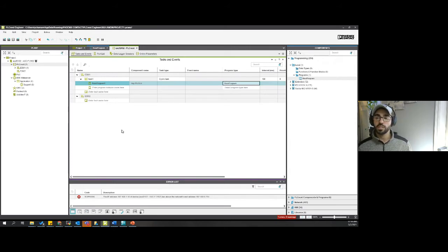We just need to make sure the OPC UA has the right configurations for this demo, okay? And again, OPC UA configurations will be different depending on what kind of OPC UA client you're connecting to. So the PLCnext controllers are OPC UA servers. So they connect to clients.